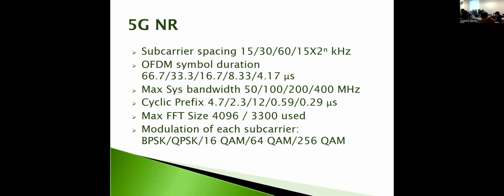All right, so our maximum FFT size is 4096. Compare that to LTE when it was more like 1024, 2048. Of course, these are powers of 2 because the FFT algorithm works most efficiently with powers of 2. And as I said, a lot of those are set to 0 as guard bands. So only 3,300 are actually used.